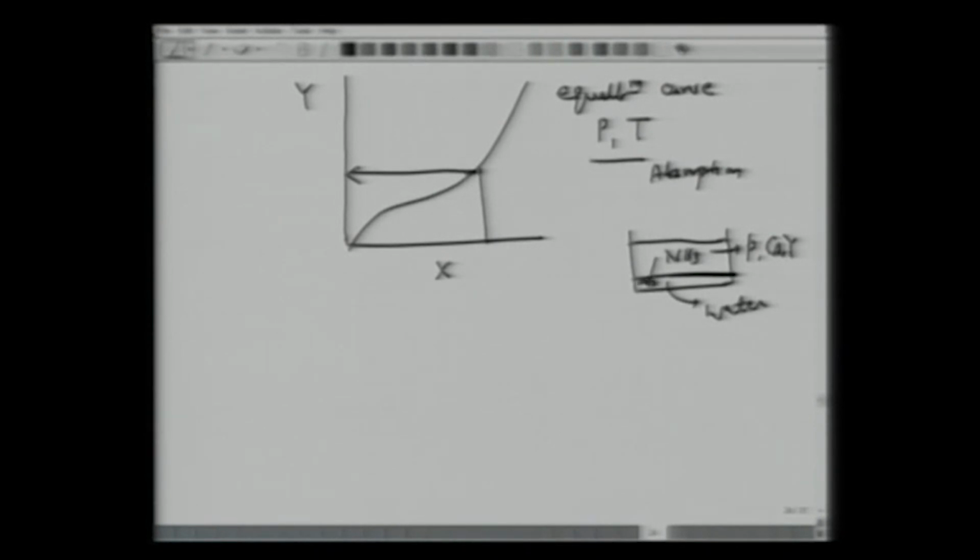We can put some stirrer here. After a long time, we measure the concentration, or mole fraction, in the gas phase and in the liquid phase, and obtain this data point. Next, one can again vary this partial pressure PA, bring it in contact with fresh water, and wait for equilibrium until we have another point. So we have obtained all these data points for the equilibrium curve.